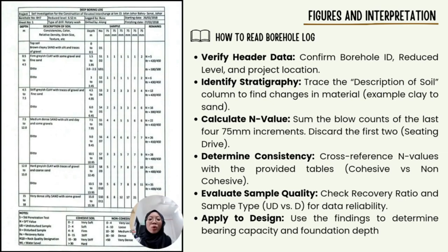So how do we read a borehole log? First, we need to verify header data: confirm the borehole ID, reduced level, and project location. Second, identify the stratigraphy. We can trace the description of the soil column to find changes in material, for example clay to sand.